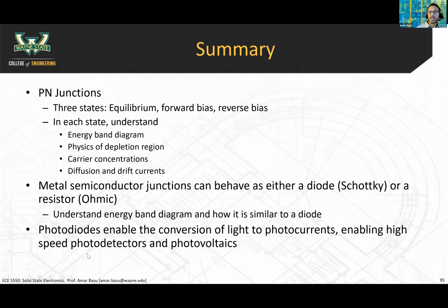The photodetector setup is region 4, where you have it in reverse bias that minimizes the diode capacitance, and it makes it operate at high speeds. And then in region 1, you can operate the diode in a photovoltaic mode where it can deliver power to a circuit when light is shined upon it.